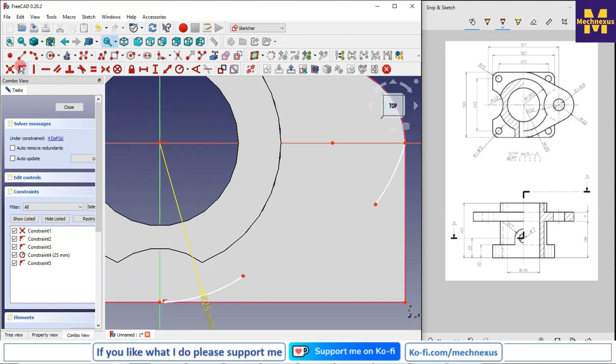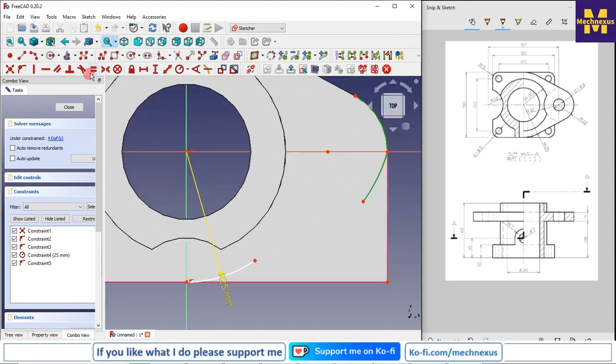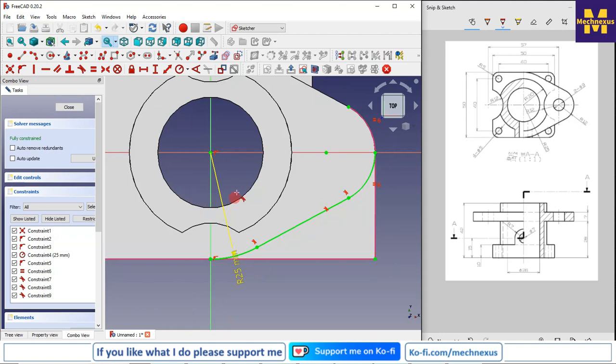This and this coincidence, and this one will be the equal, and this will be the tangent. Now I will draw the line and make it tangent with this and this. Now it is fully constrained, but we will close our profile.